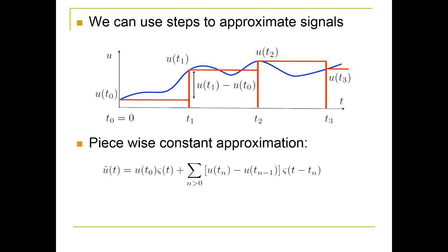So let me maybe draw this. I don't usually use the board so people can see everything on recordings, but here I think it's important. Can everyone see this? If I have a step signal like this, and I subtract from it a step signal that is shifted in time, and it looks like this, what do I get? Well, the value of this and this is the same, it's just negative. So I get a signal that looks like this. And then it's 0 for all time. Right? Can everyone see that?